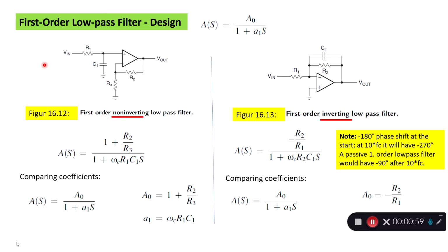But when we look at the transfer function for this circuit, we can see we have here the low pass filter, the passive one. The signal output from that filter is an input to the op-amp, and this is a non-inverting stage, so it's simply gaining the output from the filter up and then putting it out here. When we consider the transfer function of it, we can see that the general gain here is A0, so we can modify that to have a higher value than 1.